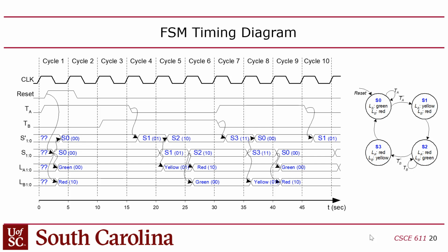Now, the traffic sensors, though, are asynchronous. They don't have to change on the clock. Typically, when you design a system where you've got multiple state machines talking in a circuit, things will be changing on the same edge of the clock because the inputs are typically coming from another sequential logic circuit, right? But in this case, I think the implication is they're coming straight from the sensor. And that's a problem, by the way. We'll talk about why that's an issue when we talk about timing analysis.